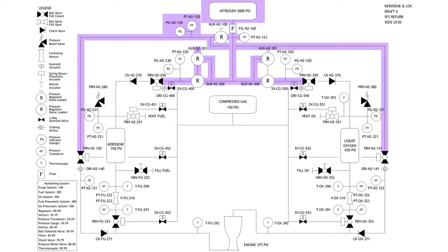So you don't want to start your dome, and we could pre-calibrate it, which is what we do now, but those inlines, we can't change while we're on the system. Those are wrench tightened. This is going to be hand dialed. So when we open our old system, what happens is that we have that 750 PSI coming out of our dome, like kick straight into the top of our propellants. And that actually is really dangerous because it can cause it to geyser. Because I mean, you have a 750 PSI brick of fluid just coming down and hammering on top of that liquid. And so it's just dangerous. We don't want to deal with it. It can cause a lot of different issues. You wet the sides of your tanks, a whole bunch of stuff that we don't want to worry about.